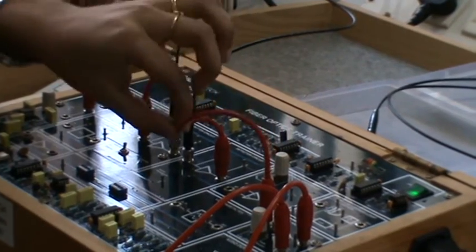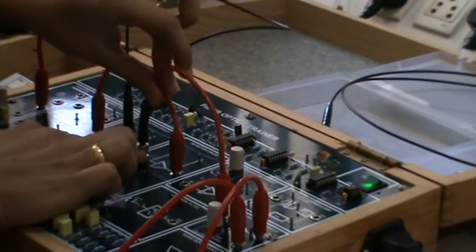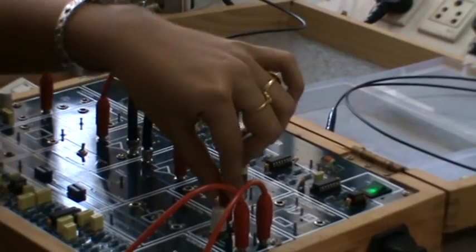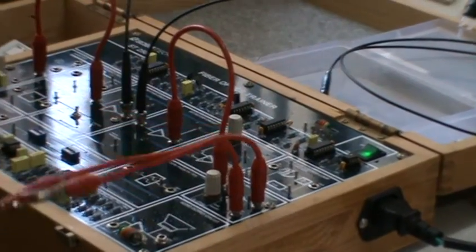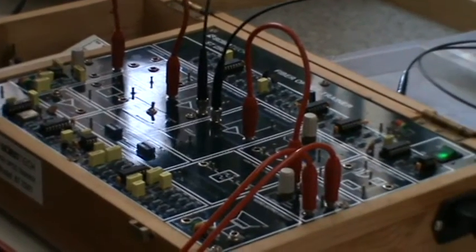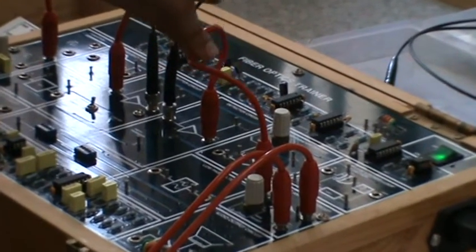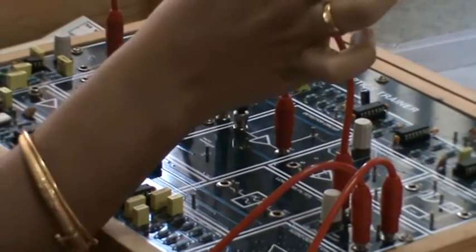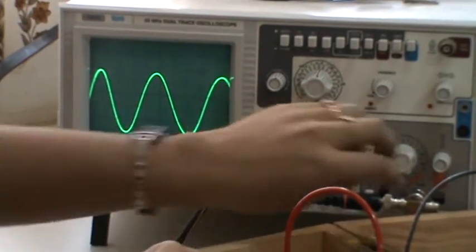Next, that OFC cable is given to the photodetector circuit, and the output of the photodetector circuit is given to an amplifier. This is an amplifier circuit, and from the amplifier I am going to observe on the CRO. These are the connections: signal generator, LED transmitter circuit, OFC cable, then the connection for the amplifier and observation. When I connected the 0.5 meter cable, I got some signal. Let me keep it at about 5 volt.